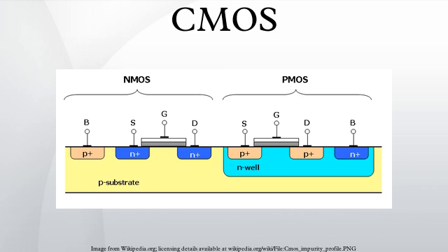An additional form of power consumption became significant in the 1990s as wires on chip became narrower and the long wires became more resistive. CMOS gates at the end of those resistive wires see slow input transitions. During the middle of these transitions, both the NMOS and PMOS logic networks are partially conductive, and current flows directly from VDD to VSS. The power thus used is called crowbar power. Careful design which avoids weakly driven long skinny wires ameliorates this effect, but crowbar power can be a substantial part of dynamic CMOS power.